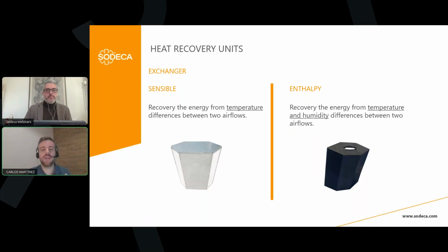On the other hand, enthalpy exchangers recover the energy from both temperature and humidity differences between two airflows. That does not mean that enthalpy exchangers are always better. We need to bear in mind that big differences between the humidity inside and outside the building are necessary in order to improve the energy exchange.